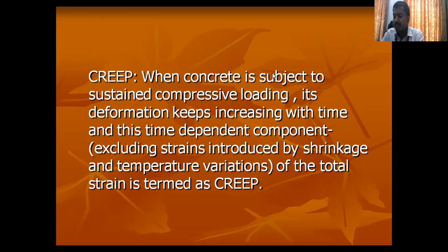So concrete is subjected to some loading, and because of this, a deformation is going to happen. When the concrete is subjected to loading with a constant deformation, that deformation goes on increasing with respect to time. This is the time dependent component of the total strain. We call it creep.